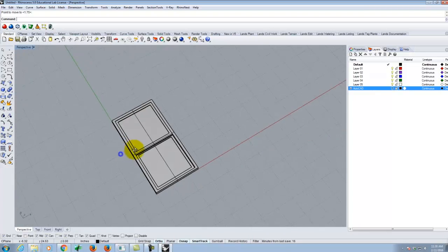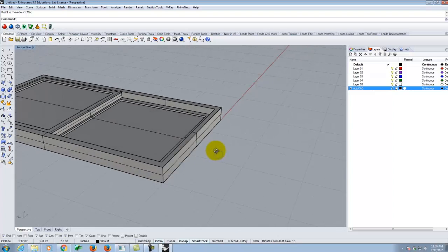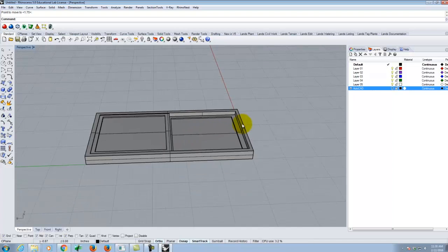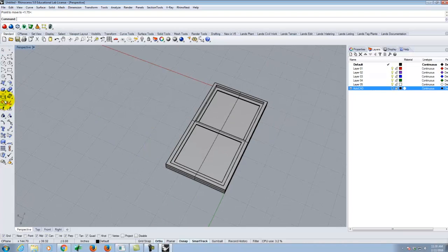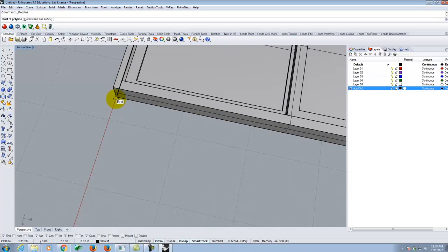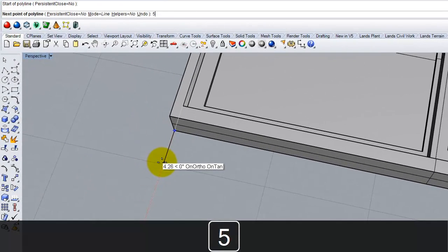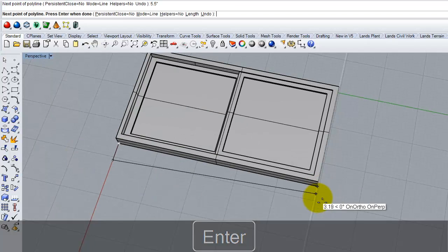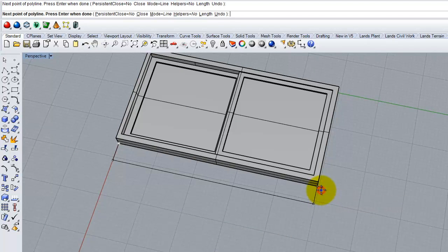Okay? I could take this a step further, and I could actually add some trim around the window. Because in reality, if I were to glue it on the side of a wall, it would have some trim around it. So let's go ahead and build some trim. I can do this just with the box corner-to-corner tool, or I can start drawing. Depends. So let's say we'll go out. Maybe we'll do 2x6 trim. So this would be 5.5 inches. And we'll go till it's there. There's one piece.